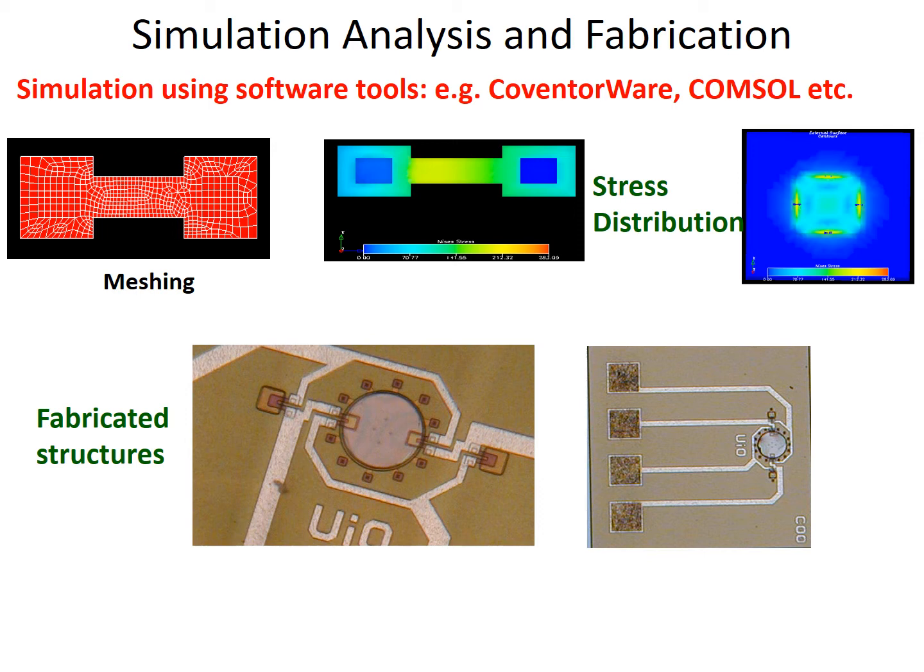Rather, to reduce the complexities, the costs involved, or the labor and efforts during the fabrication process, what we can do, instead of going into the actual fabrication, is that before that we do some sort of simulation and analysis, right? Once we are satisfied with the simulation or the analysis, then we will go for the fabrication for that particular dimension, right? So that's why for simulating the MEMS device, we have certain dedicated software tools like CoventorWare, COMSOL. So these are some of the tools.